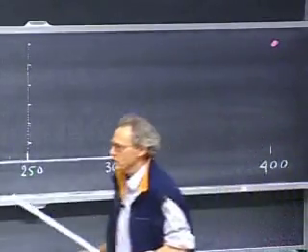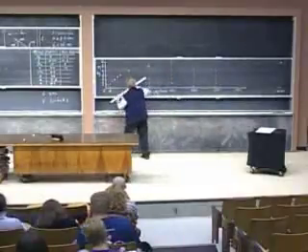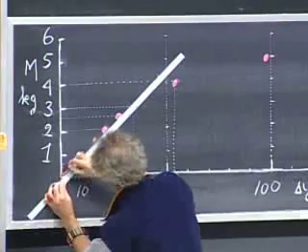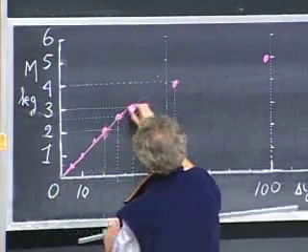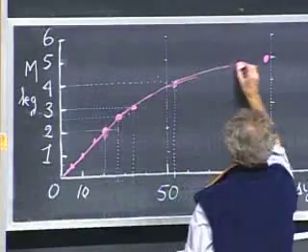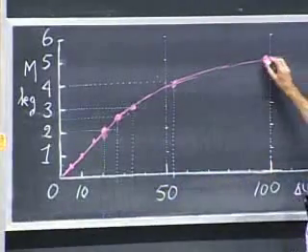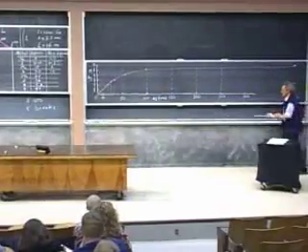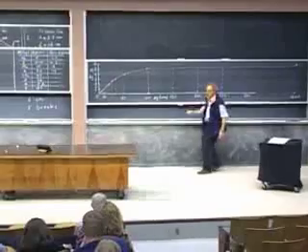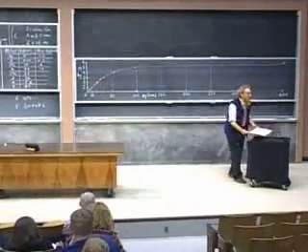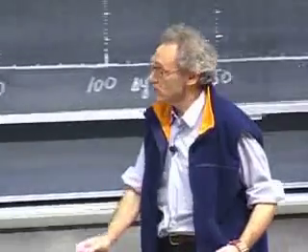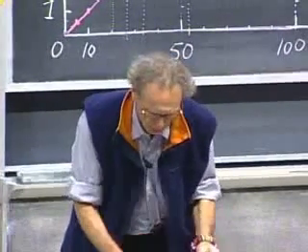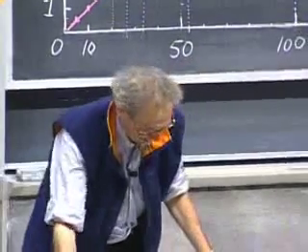But look how wonderful this is, isn't it? Isn't that a great curve? Very linear in the beginning, and it starts to bend over, and you draw that line any way you want to. And then it breaks. And so we can now actually make an attempt to calculate Young's modulus from the data. Of course, you'll have to select a portion where you think that the data are reasonably linear.